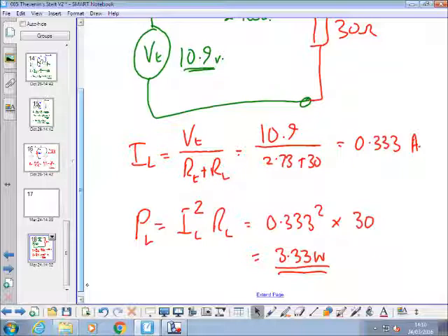We could short out the source and put an ohm meter on and find the Thevenin resistance, and show that it would act the same when we connected up just the Thevenin voltage and a series resistance according to the Thevenin resistance, and connect the load resistor back in and see we got more or less the same current. Would that help to understand where this is coming from, or at least prove it?